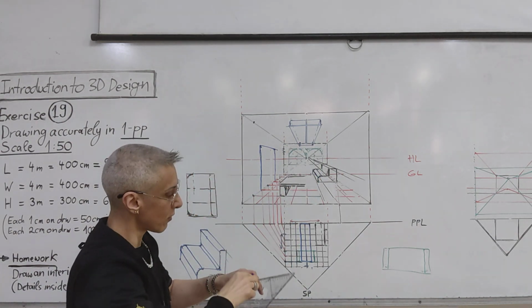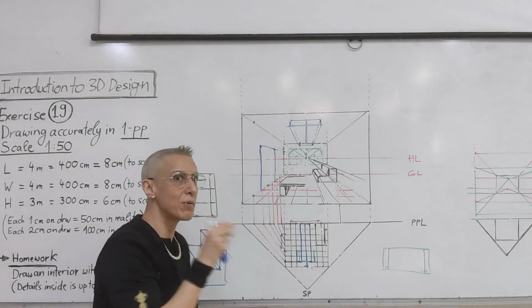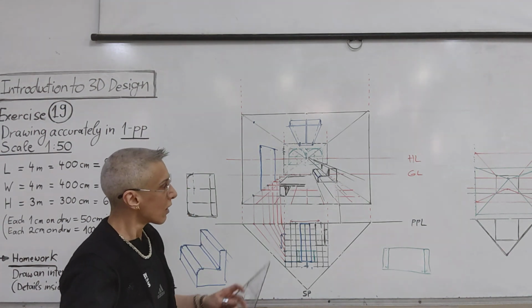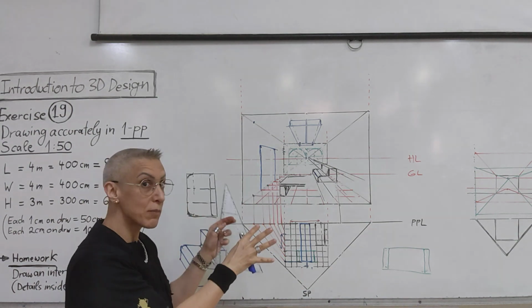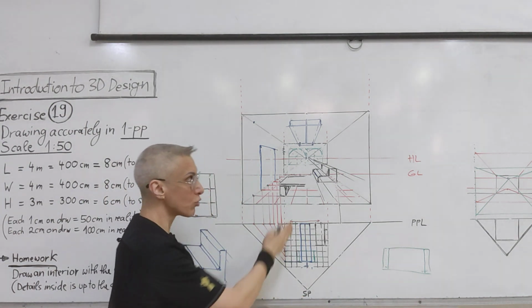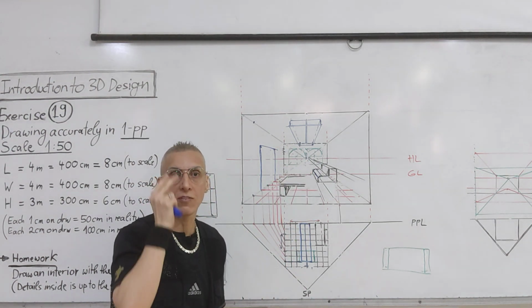So on the drawing, when you draw with pencil, please draw very lightly, because as you can see, it can become so many lines and overcrowded. So you don't want thick lines like these pens, because it will become confusing, okay? So very thin lines. After you finish constructing everything, then you will draw the objects heavier.